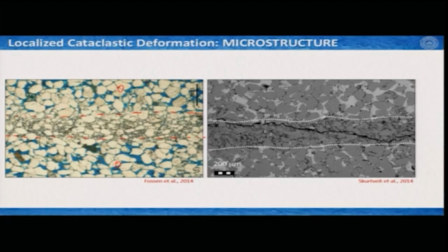If we measure statistically, the grain sizes here are a little reduced from what we see outside, and the porosity has also reduced. The number of small or finer grains along this narrow zone is quite significant, and as I said, this length is about 1 millimeter. So, this is a very narrow or thin zone.